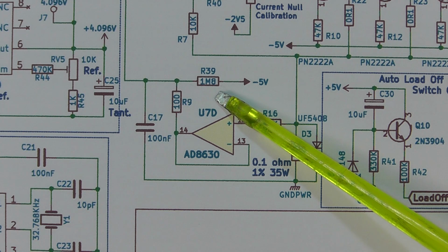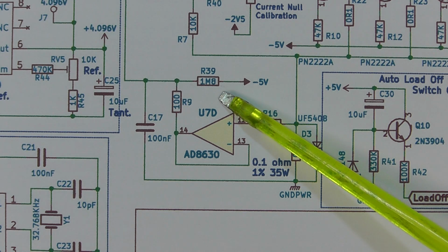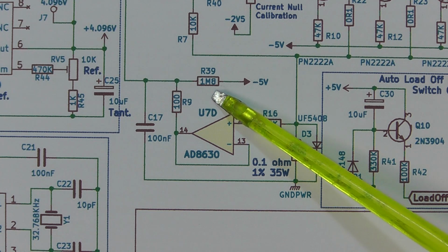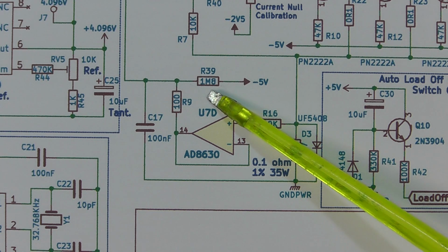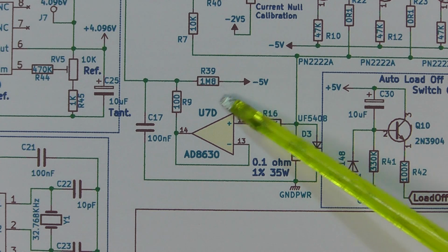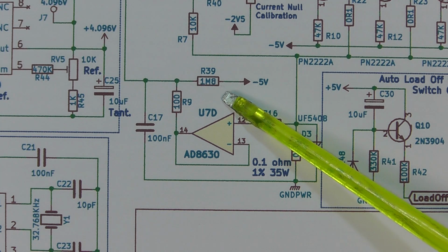There is a slight discrepancy between the lower and the higher current readings of maybe a few milliamps, and if you wanted to play with that resistor, you could replace the 1.8 megohm resistor with a 1 megohm resistor, and then add in series with that a little variable trimmer, let's say something like another 1 meg trimmer.